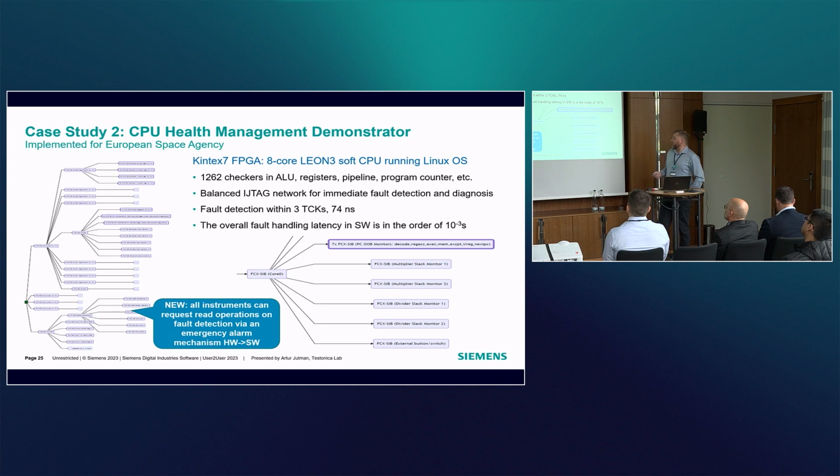This particular demonstrator involved an 8-core CPU implemented on FPGA, and we inserted over 1,200 different checkers into this 8-core CPU in different modules like ALUs, registers, pipeline, program counter, and so on.